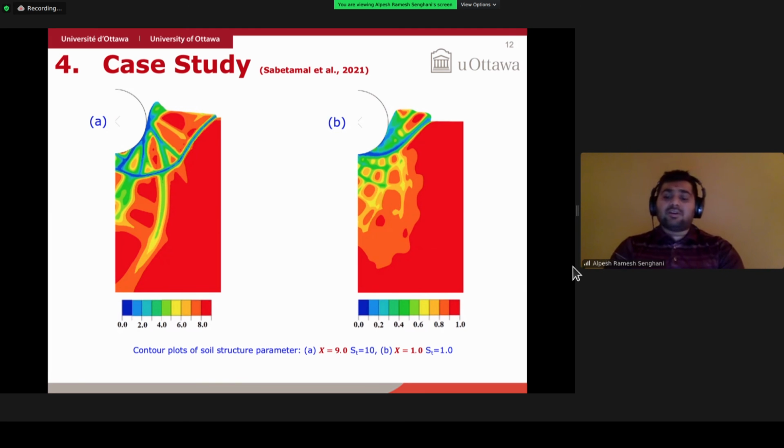So in sensitivity of 10, there is a lot of blue, right deep inside near the slip surface and into the polygons as well. However, in the sensitivity of 2, the blue is just along the slip surface. It doesn't go that deep with the 0.5 depth of the pipe we have.